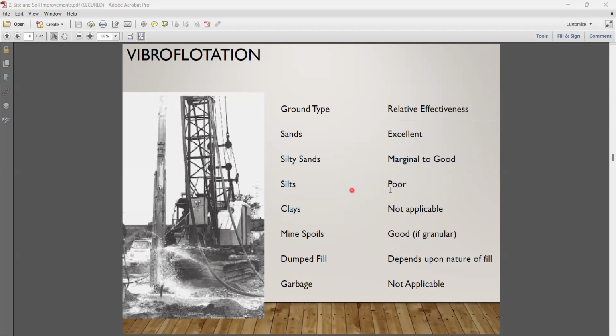If you have silty sand or silts, it's also not very good. It's only useful for sand. So while applying the vibration, like the previous method, we also apply some water, which helps the particles come together and the voids to be released. Same as in the Proctor compaction method, if you remember: initially, water helps soil particles go to another place and compact more.